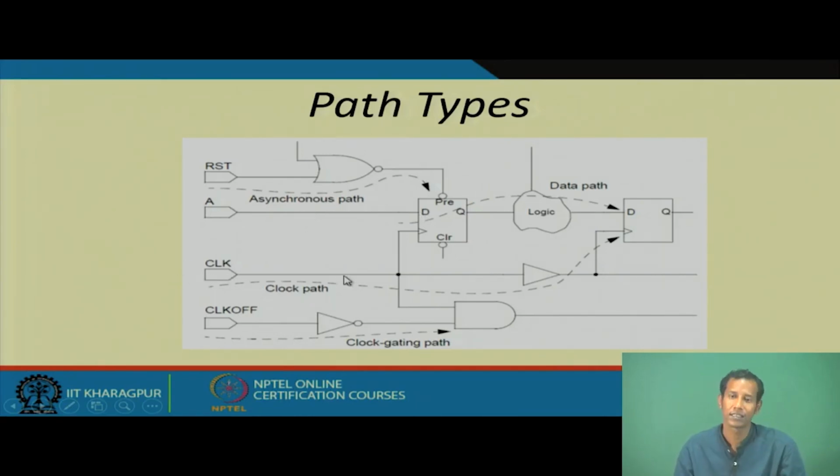Now, the clock is continuously running. So, though this data is not changing its value, it is basically in the idle state. Because of this clock running, the whole circuit will run continuously, and if I run the circuit continuously, it will consume power.